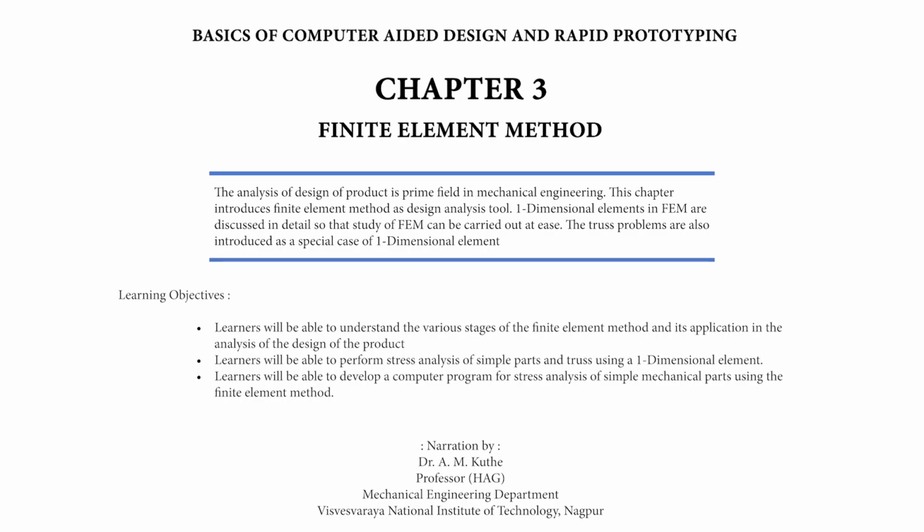Para 3.1.4 Assembly. The equilibrium equation for all the elements is assembled to form a global equilibrium equation. The global equilibrium equation consists of the displacement parameters of all the nodes of the continuum. Assembly of all the elemental equations is necessary as nodes are shared by the elements to form a global equilibrium equation.